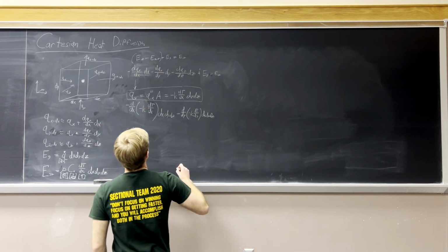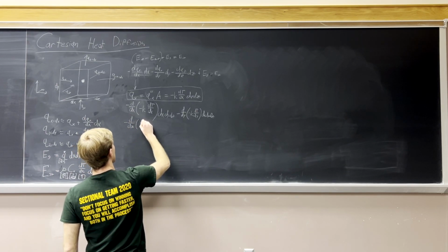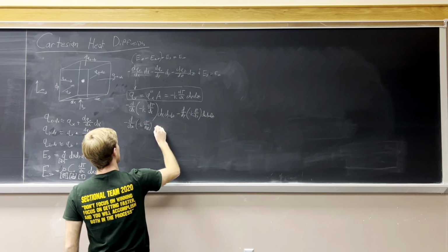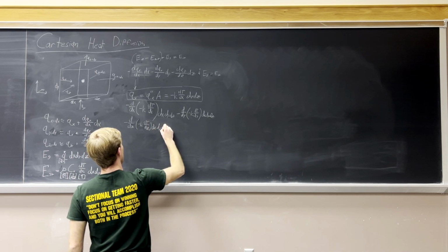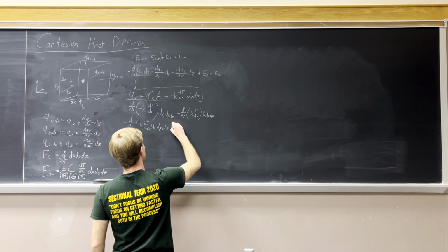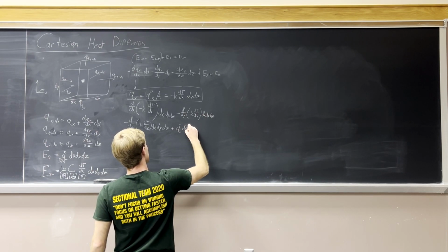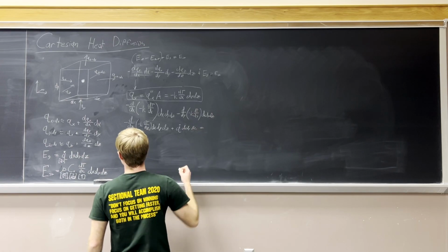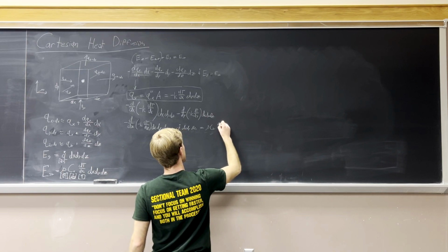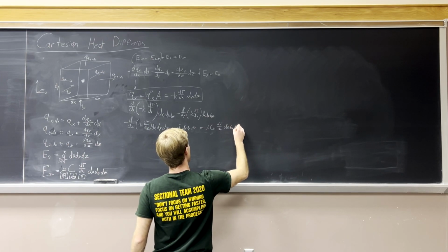And then I'm going to wrap around here and say minus d over dz of negative k dt over dz multiplied by dx dy dz. And now this is where I'm going to write in our E of g right here. So plus E of g. Well, E of g is just our q flow times dx dy dz. That's going to be equal to our energy storage, which I can write in as well. It's going to be rho cv dT over dt multiplied by dx dy and dz.